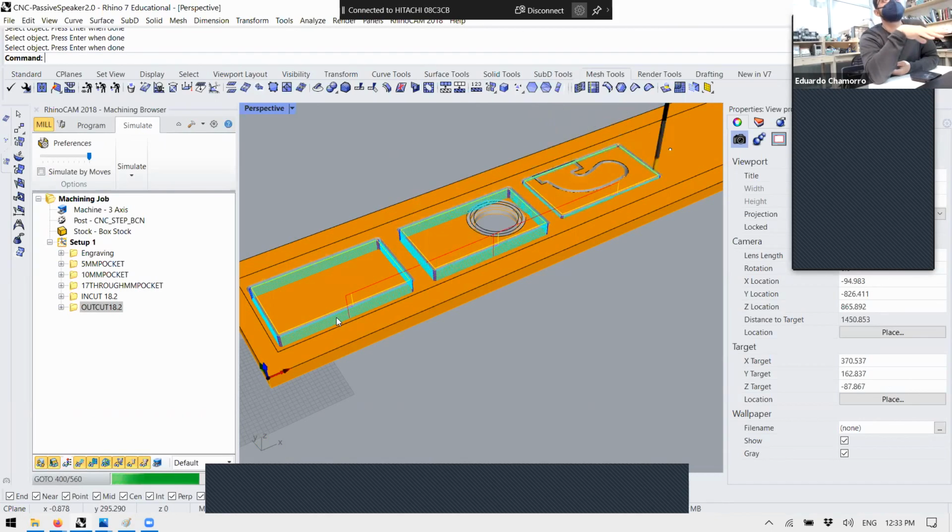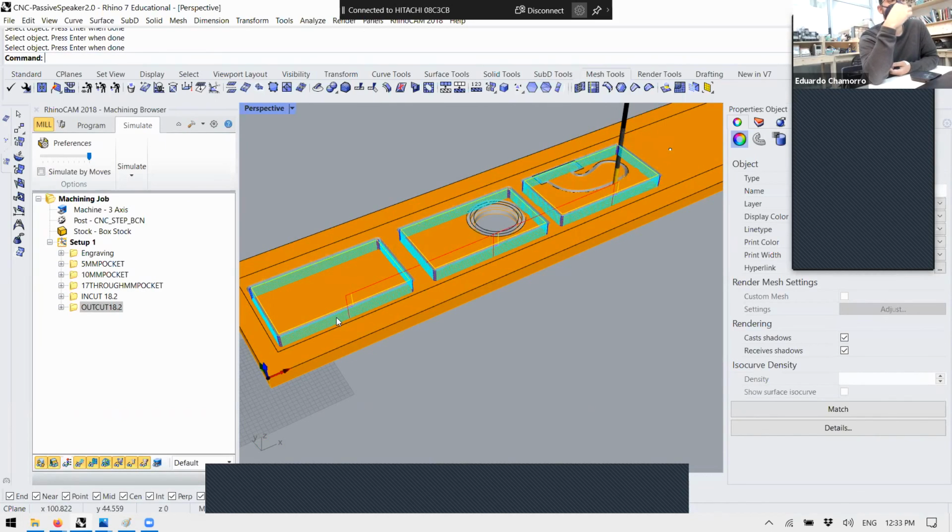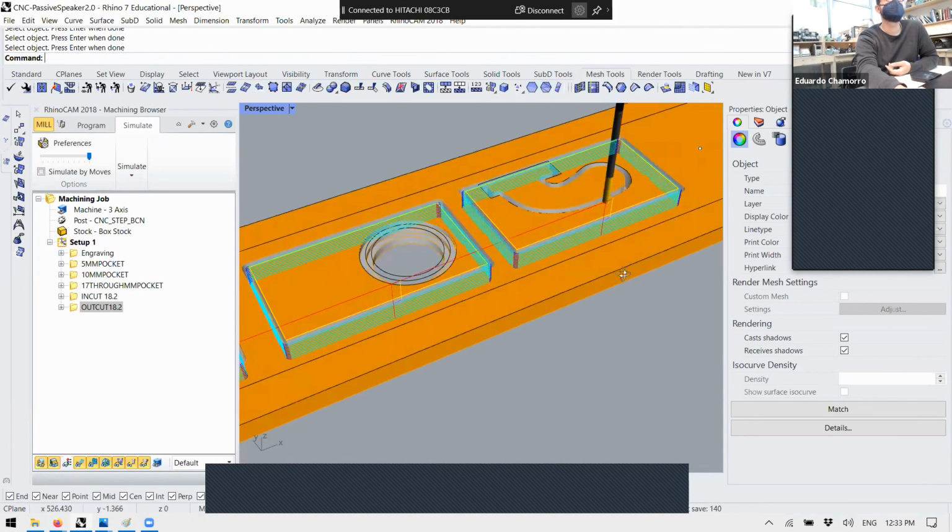In 2D simulation, this goes quite fast. In 3-dimensional simulation, this is awfully slow to calculate. Depends on the simulation, but if you are making a really complex 3-dimensional mill, this can take half an hour to calculate the simulation. Even sometimes more than the milling time.